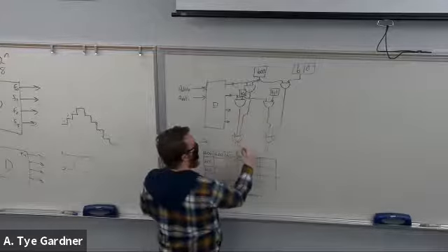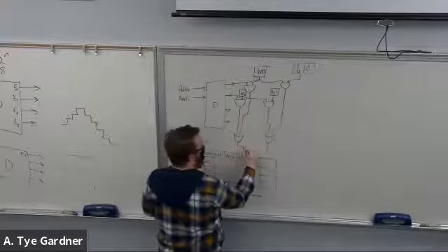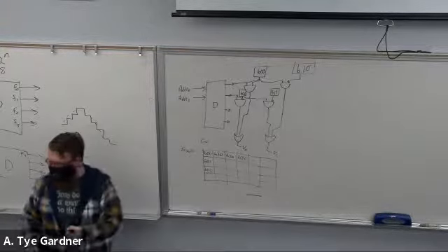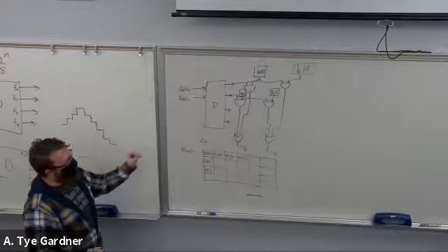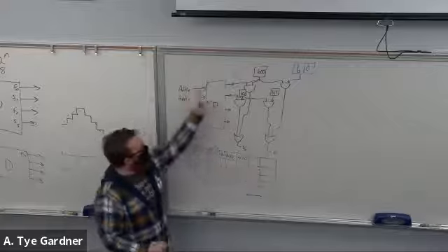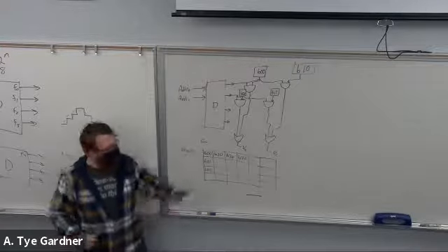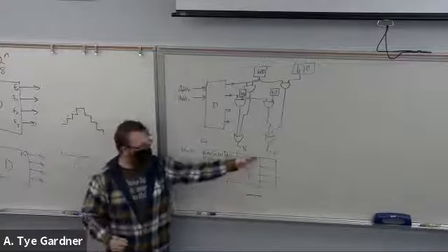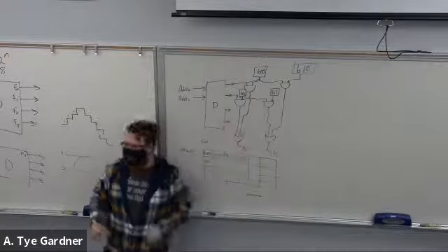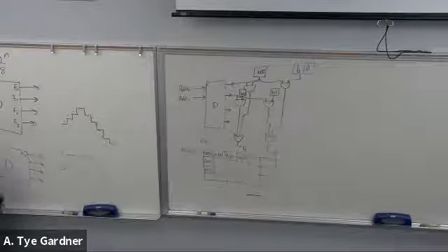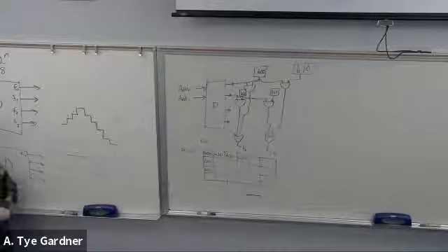And now I'm going to have a bit vector, I'll just call it V0, V1. So now my output is the result of the address lookup. So it's going to look up the contents of this entire row based on this 1 hot decoder. And I can use V0 and V1. And 2, 3, 4, 5, right? Because it's a 6-bit, I just didn't draw the rest. So that's a real world application of decoders. And that's also addressable memory.